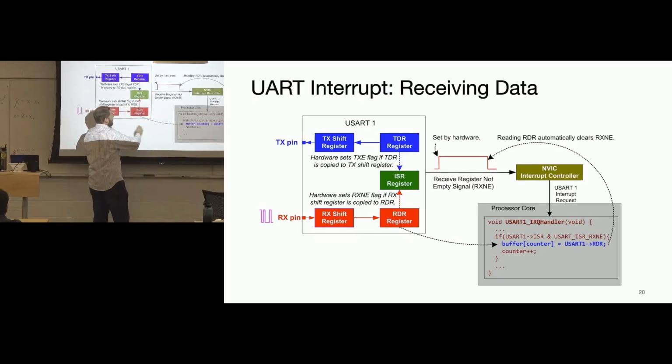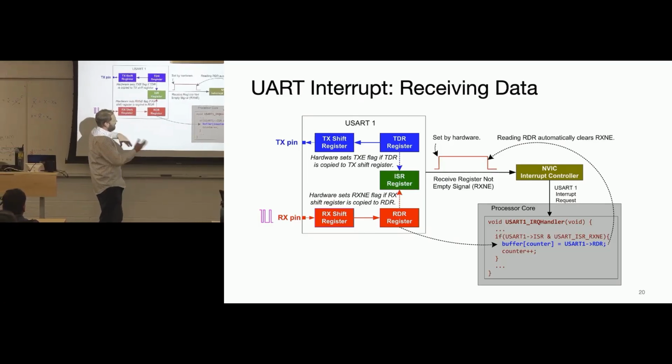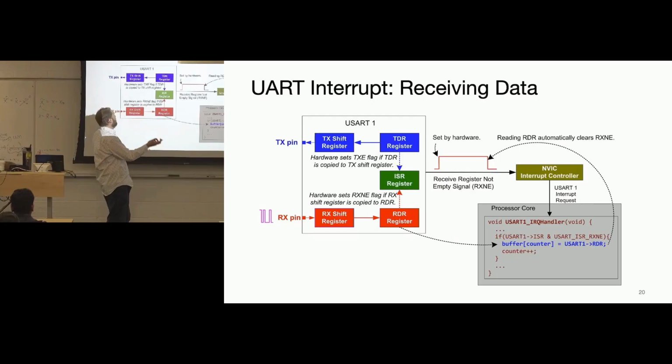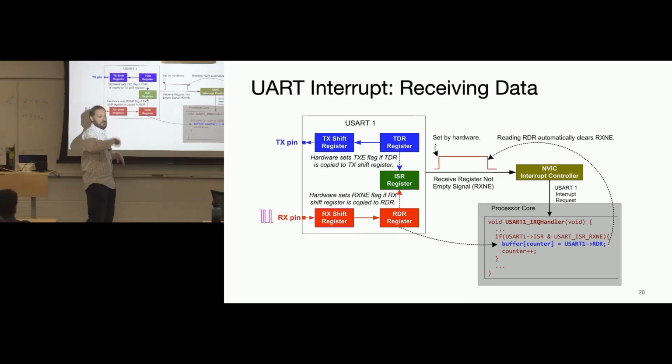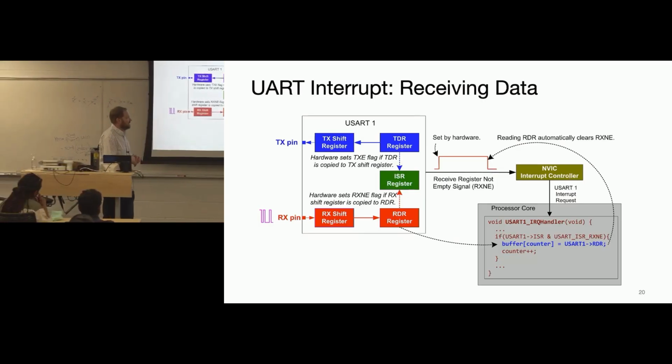Right. So now you have essentially a method for the ISRs to do flow control and send multiple characters at a time. And so again, the programming paradigm is you do a bunch of setup. You go through, and you set up these registers to be on and connected to the GPIO pins and sending data at particular baud rates and all those things. And then you're either pushing data into and calling an ISR, so you're saying, okay, I want you to push this data out for me, or you're waiting for data to come in, you pop in the ISR, read this buffer, put it into storage, and then get out of your ISR. And then in main, you can do some function on top of the data that you put in memory.